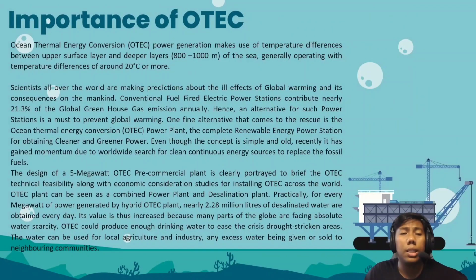Next is the importance of OTEC. We know that OTEC needs a temperature difference between the surface layer and the deeper layers at around 1000 meters. It generally operates with a temperature difference of 20 degrees Celsius.